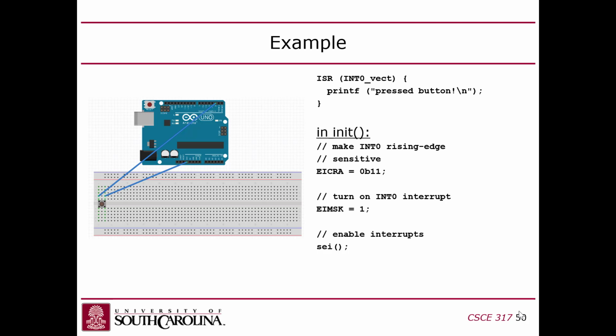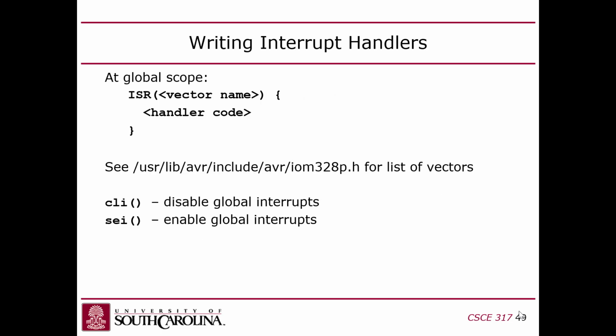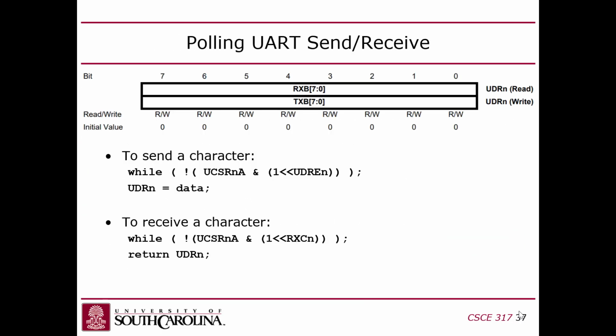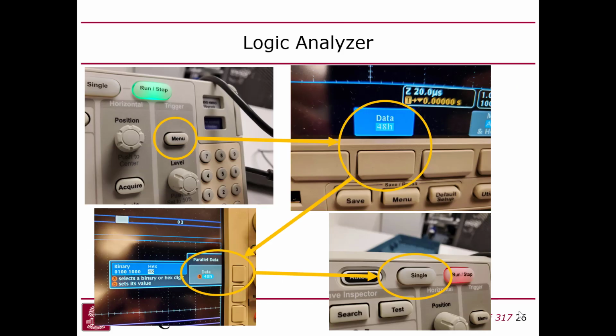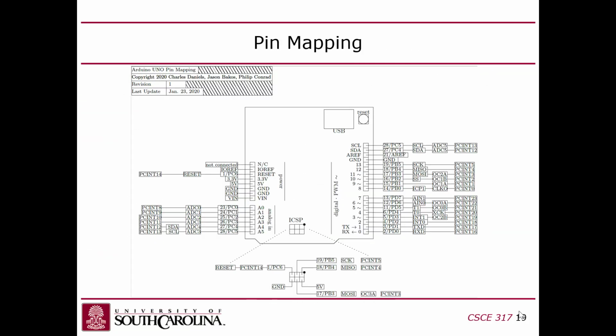So I've got the board here, and I'm going to take this pin 2, and again, you wouldn't know this unless you look at our diagrams or find it in the data sheet. But if you look over here at this pin 2, I don't know if you can read it in the back, it says interrupt 0, interrupt 1.